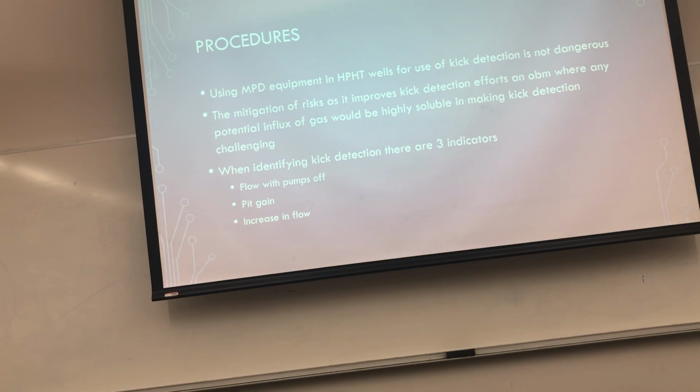So now we're going to get into the procedures of actually drilling in high pressure, high temperature wells. Using the equipment for kick detection is not dangerous. What is dangerous and can provide challenges is the mitigation of risk as it improves kick detection efforts in OBM, where any potential influx of gas would be highly soluble, making kick detection challenging. When identifying a kick, there are three main indicators: the flow when the pumps are off, pit gain, and an increased inflow.